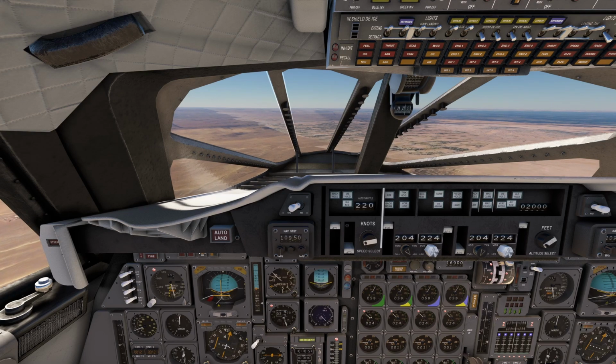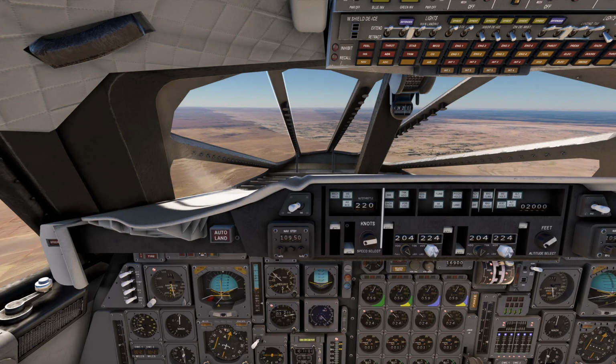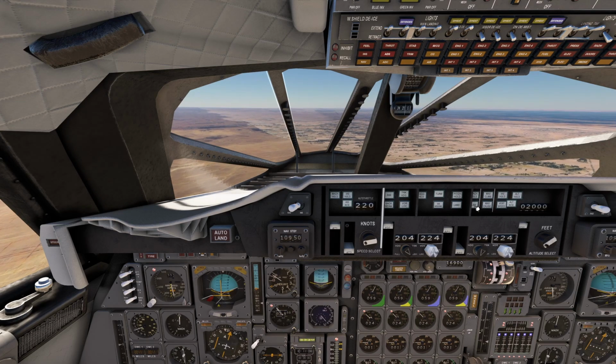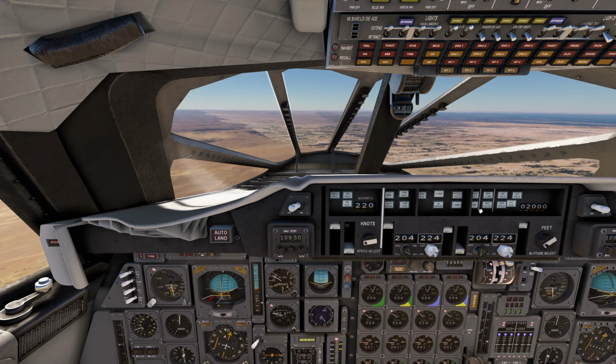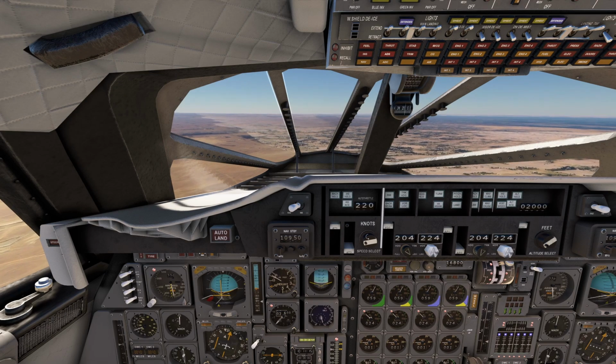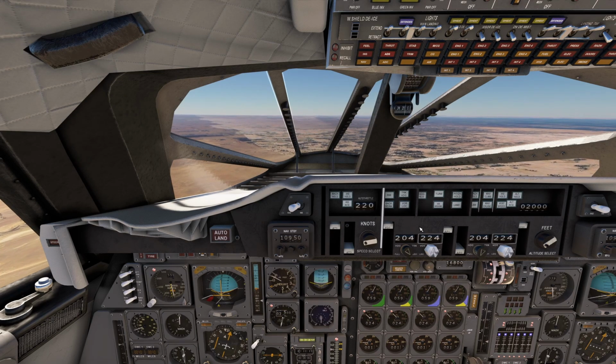Still too fast, but approaching entry point 2,000 feet. Expecting ILS to become alive coming in, and then go to glide slope. Visor down if we can get our speed under control, which at the moment is too high.